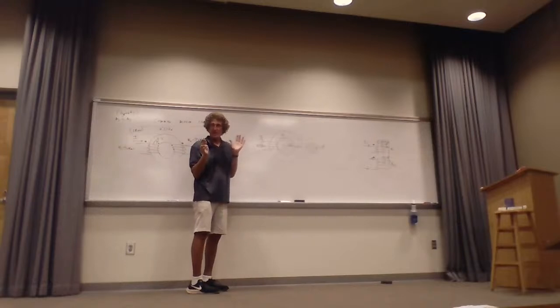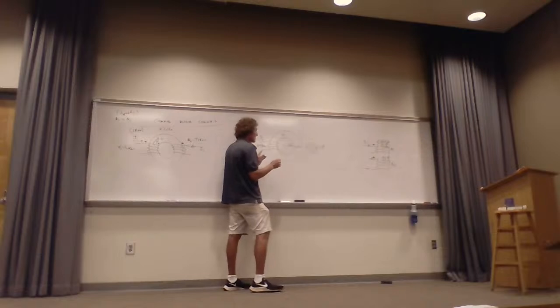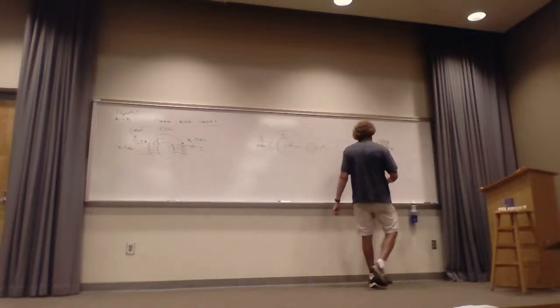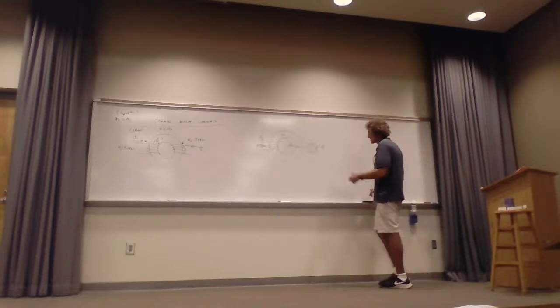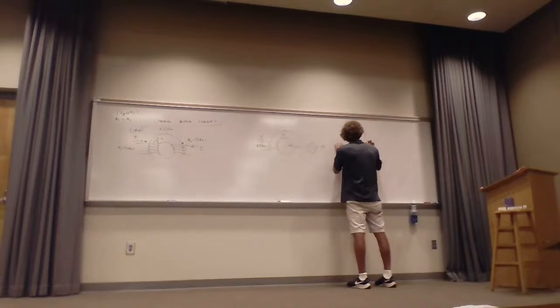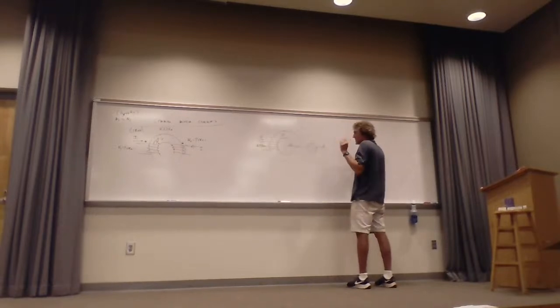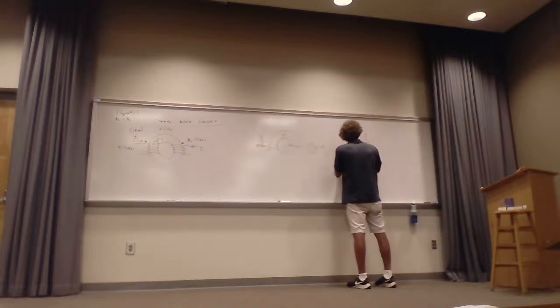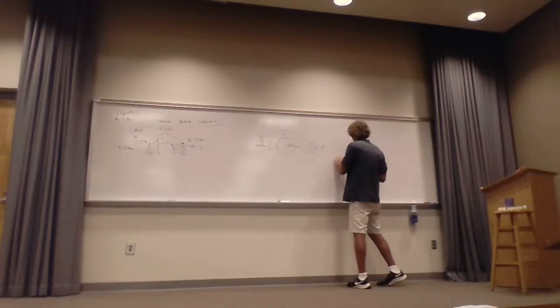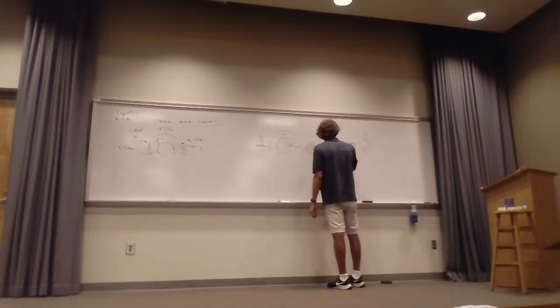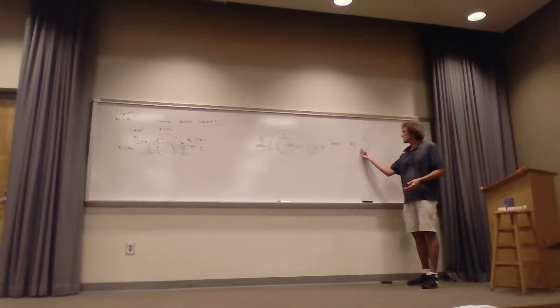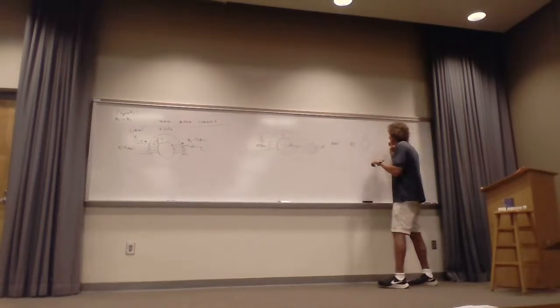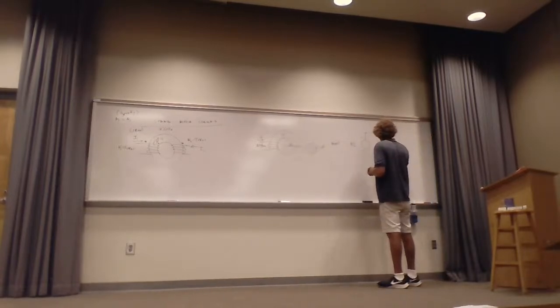With me? All right. Well, I can see that really this is a simple magnetic circuit. And since I assume I can figure out what mu is, it's just mu relative times mu zero, I can draw an equivalent, quote, electrical circuit. It's really a magnetic circuit only with an electrical look to it. This becomes Ni. That's called a magnetomotive force. Do you remember that? It's just like EMF is the electromotive force. It's just like a voltage. And then you have a reluctance here.